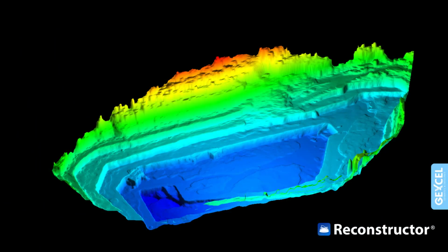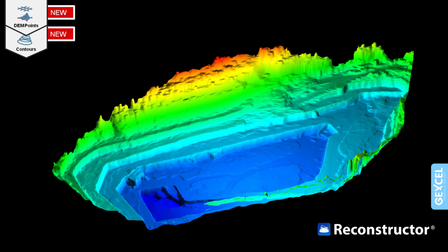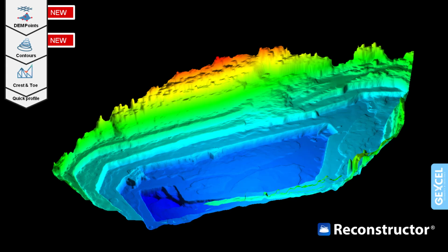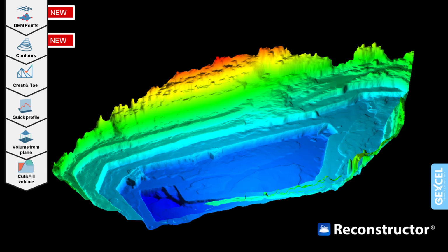We will see how the new Reconstructor 4.2 release can speed up your job in mining and land environment areas, sensibly increasing your productivity. Starting from the creation of a DEM model from a point cloud or a mesh, we will move on extracting isolines and contours, crest and toe, the discontinuity of the 3D model, quick profiles, and we will experience how to compute volume and cut and fill volume as well. This workflow has something for everyone.